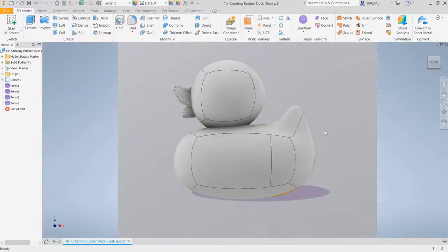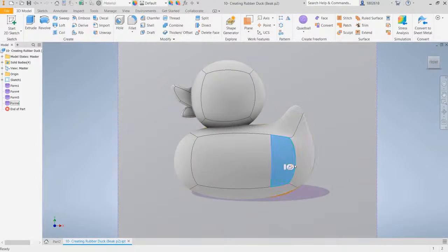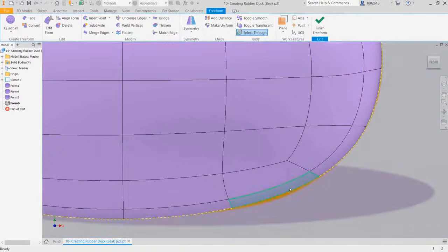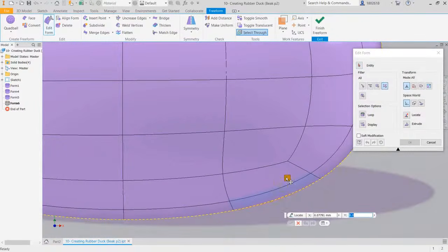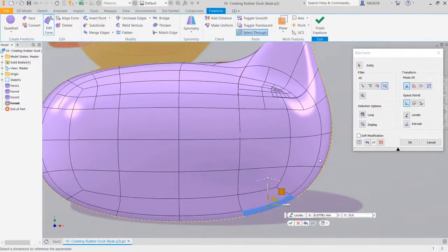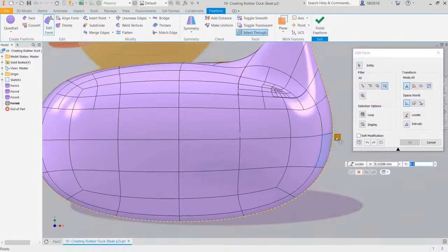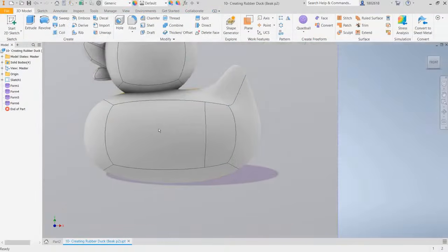And as you can see, our figure is not aligned with the reference image. Left click, click the edit form, zoom in your view using your mouse wheel, click the edit form, then drag this manipulator. Zoom out your view using your mouse wheel, then press enter. For this side, click the edit form, use the drag manipulator, then press enter. Then select finish freeform on the exit panel.